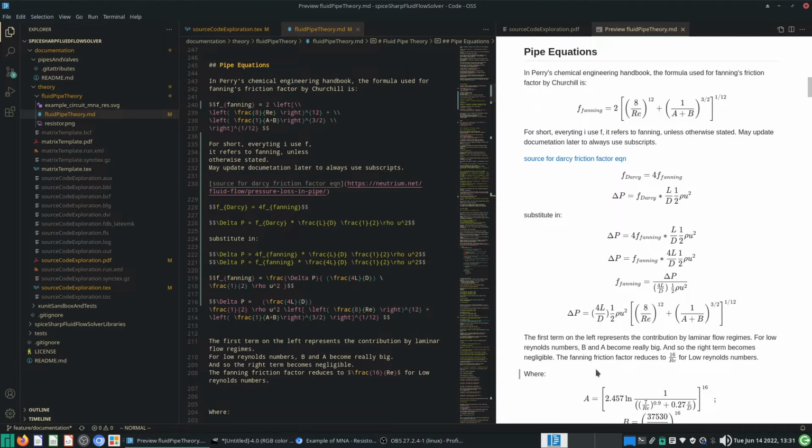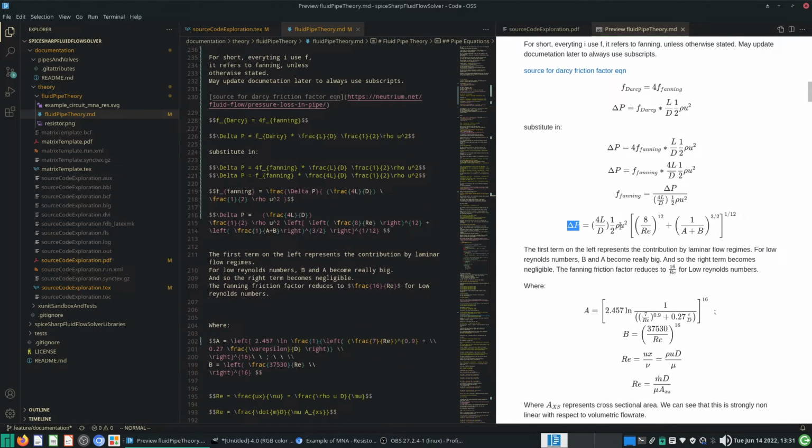The only two things we are concerned with are the pressure drop, or rather kinematic pressure change, and the mass flow rate, which is directly related to velocity, right? Of course, we can change the Reynolds number to velocity, but I think it's easier to change the velocity into some form of Reynolds number, and then we get the mass flow rate from there at the end of the day. Because dimensionless numbers are easier to work with, we do not need to concern ourselves with units. So we'll try to keep it in a non-dimensional form.